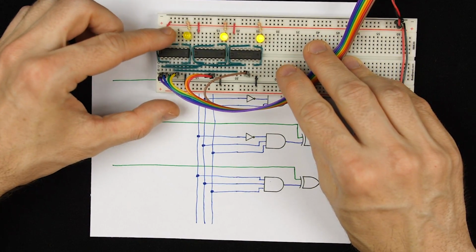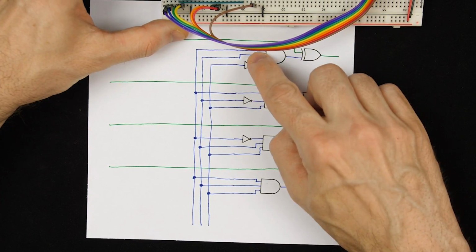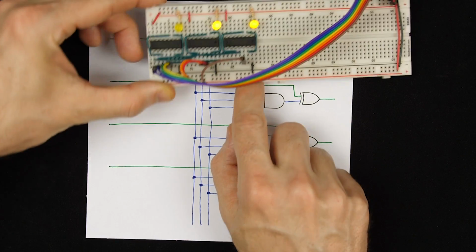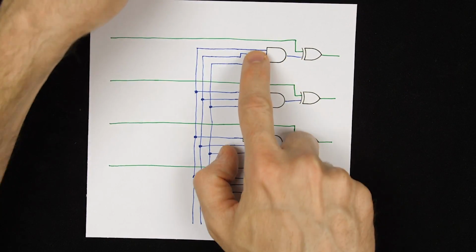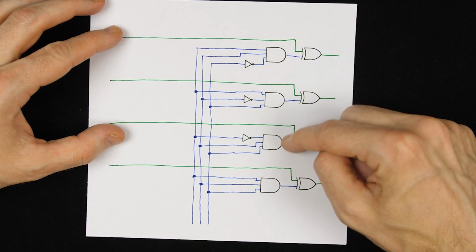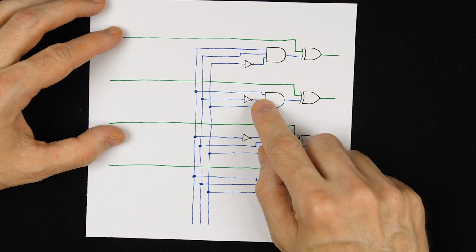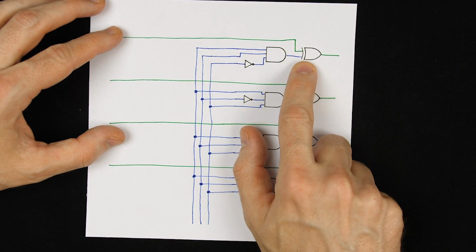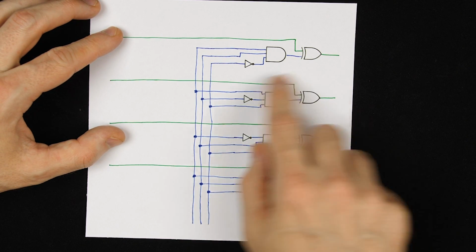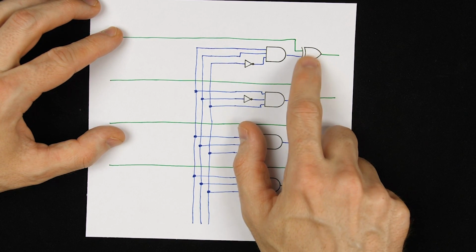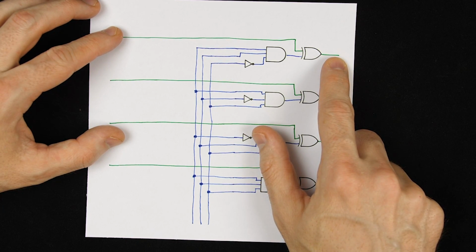So in this case, we see that the error is at 011. So 011 is bit position 3. So that means that the error here is in bit position 3, which will activate this AND gate. Of course, none of these others will be activated because they're selecting for different combinations of values. But this one will be on. And so that will tell this XOR gate to flip its input. And the other ones won't flip their inputs, so they'll just pass through. But this one will flip, which will have the effect of correcting the bit that was incorrect.